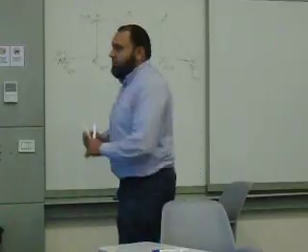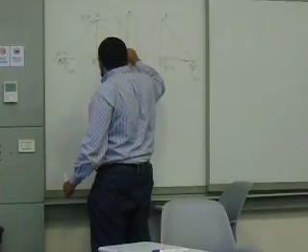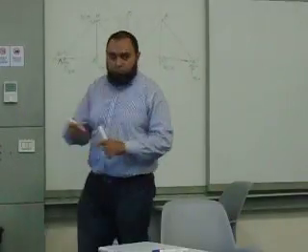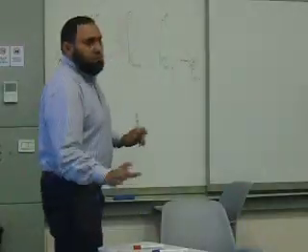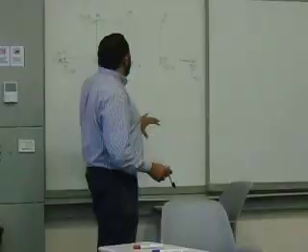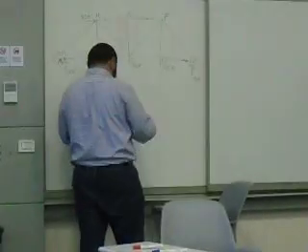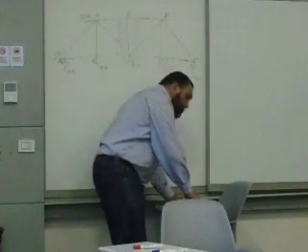I'll mark some members here. I only need these ones. I don't need anything else. But there's no need to go and solve all of the cross members. No, I'm not doing that. I'll do what we call a section.